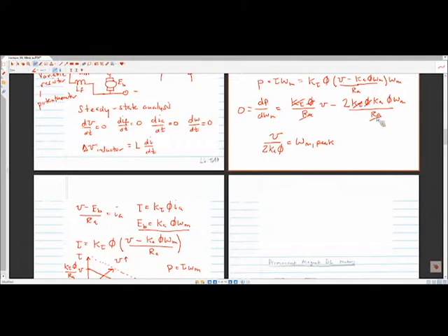I follow what you did, but if you look at the torque versus omega plot, since it's a linear line, I would have thought it was linearly proportional, so if you just multiply torque times the speed, it would be constant the whole way. Yeah, the relation between torque and speed is linear, right? But the expression for power is torque times speed again, so you now get an omega m squared term in there. Okay, I was thinking about it wrong. Does that make sense? Yeah.